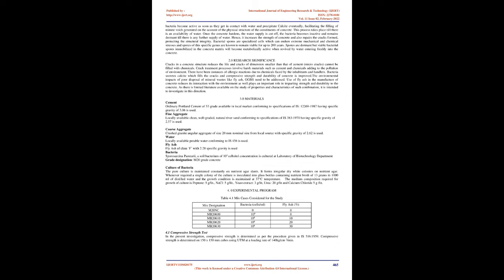1.0 Introduction. Concrete is a widely used building material in the construction industry. Due to various reasons it has the tendency to crack. These cracks vary in size, from a few microns to a few centimeters, and often they may occur at places which cannot be accessed. Cracks allow moisture to enter and cause corrosion of reinforcement and impart irregular stress distribution across the section. This makes the section weak to carry any further load. Hence, these cracks should be treated as early as possible to ensure the safety of the structure.